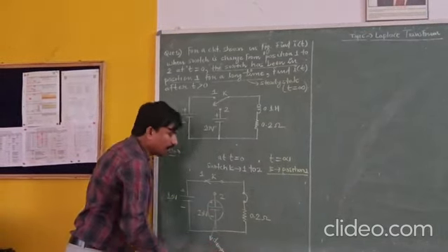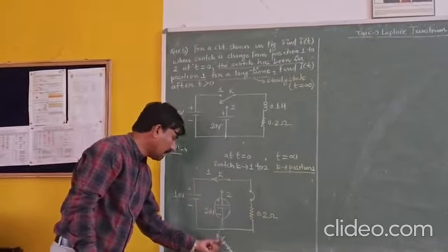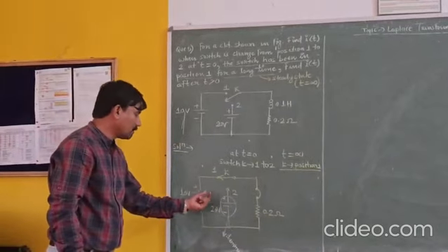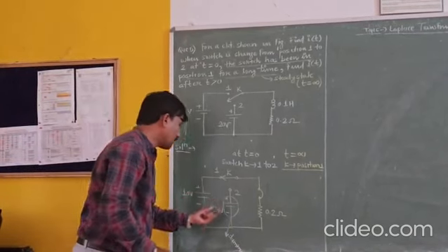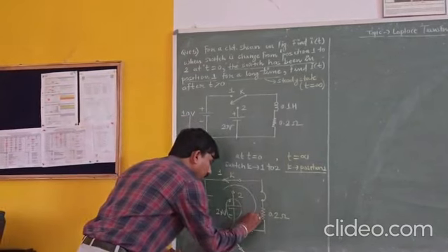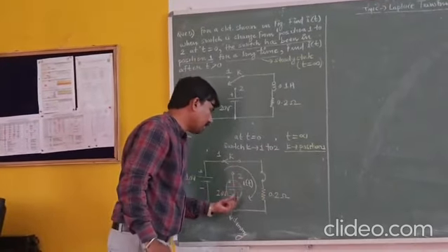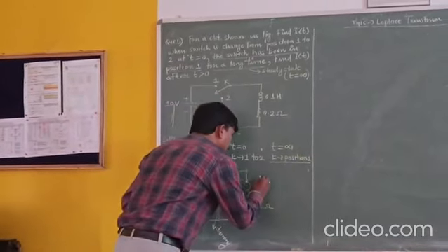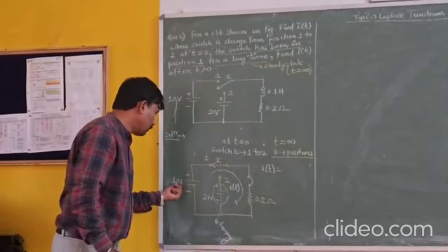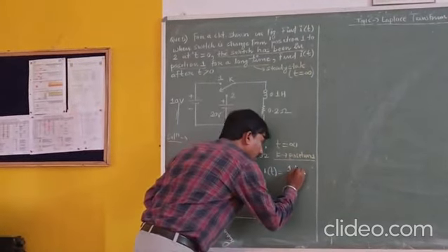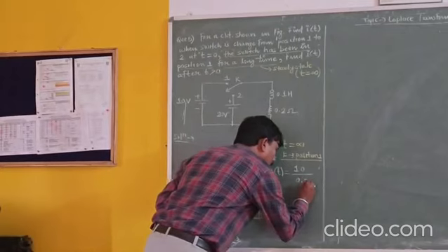Whenever we are going to solve such a circuit, if a dummy element is there, we have to always ignore it. Now if I want to calculate the current flowing inside this circuit, that is i(t) at the condition t equals infinity, then i(t) equals total voltage, that is 10 volt, divided by total resistance of the circuit, that is 0.2 ohm.